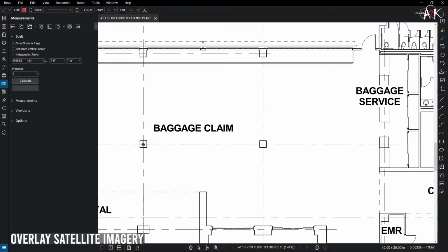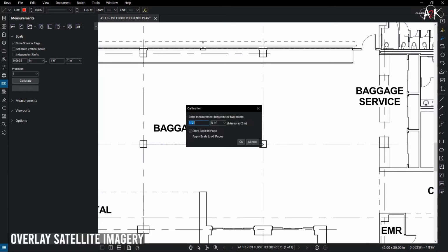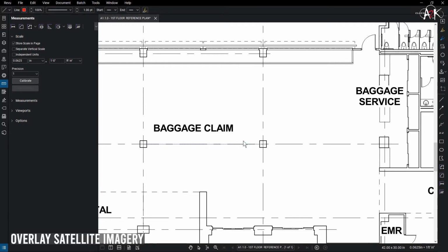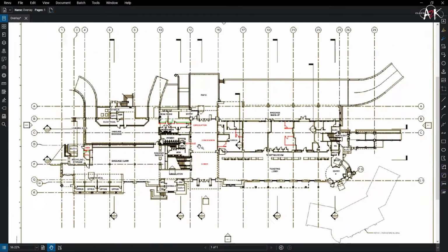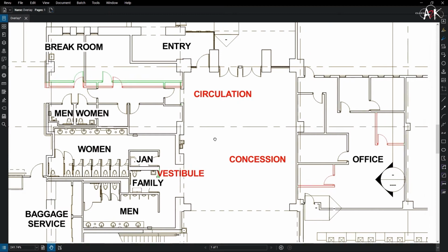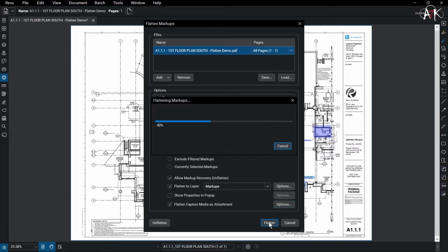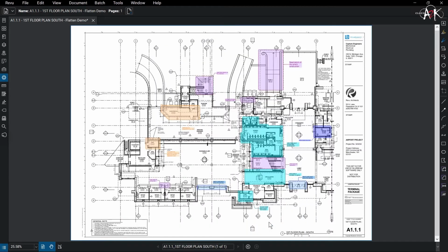If the scale isn't available, you're still in luck. Maybe you know the curb-to-curb dimension of a building footprint. You can calibrate from that too. Once you have the image calibrated, you can start to overlay markups for easements, utilities, signage, or even site staging material and equipment. If you're doing resurfacing or flat work, you could even do material estimates.